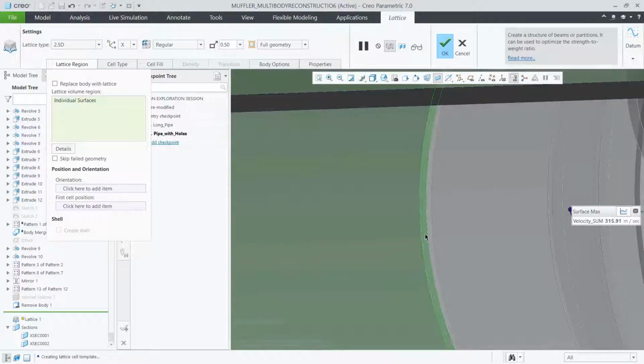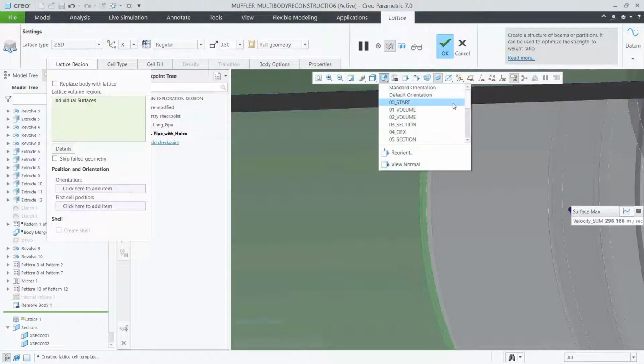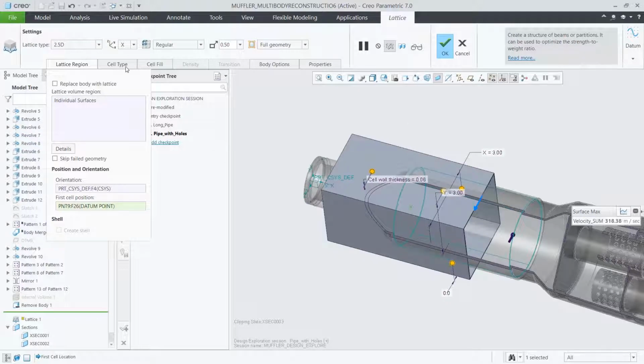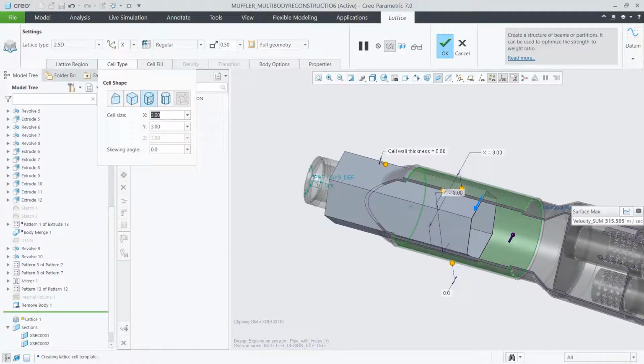And instead of this being just wide open, or in this case drilled holes, let's make it something a little more complex. Let's use the Creo additive manufacturing capability, start here in the center, and put in a 2.5D lattice that's more of a hexagon shape.